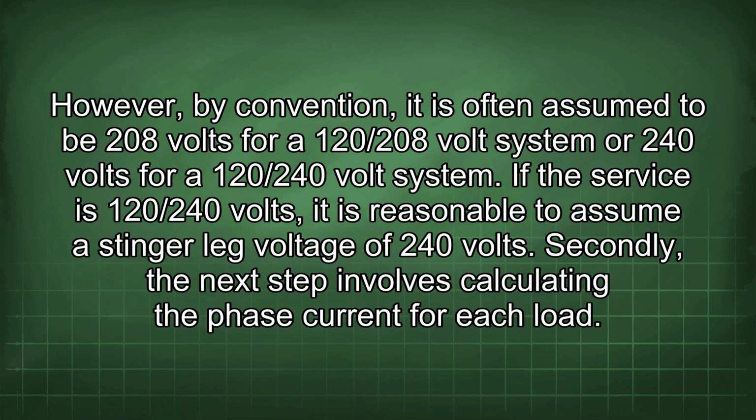120/208 volt system or 240 volts for a 120/240 volt system. If the service is 120/240 volts, it is reasonable to assume a stinger leg voltage of 240 volts. Secondly, the next step involves calculating the phase current for each load.